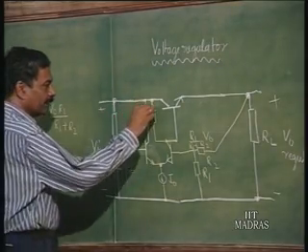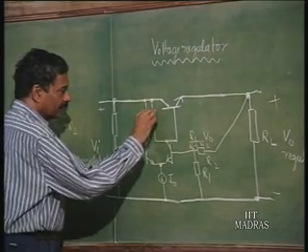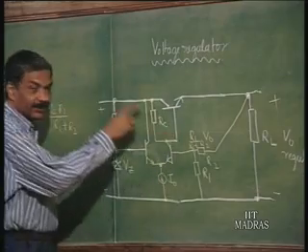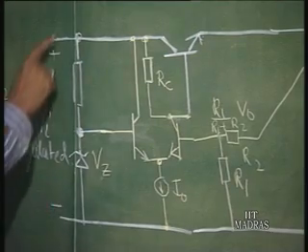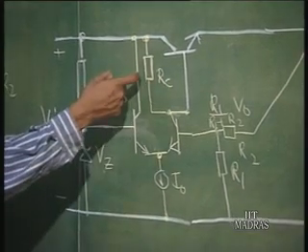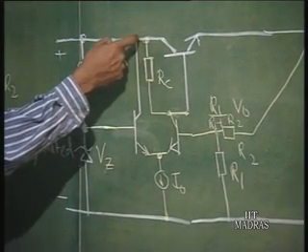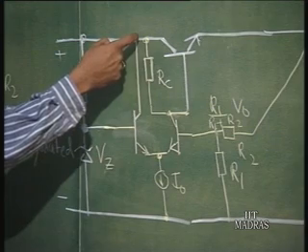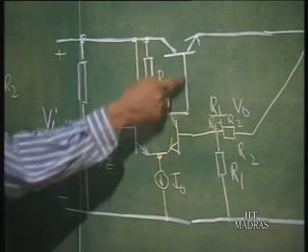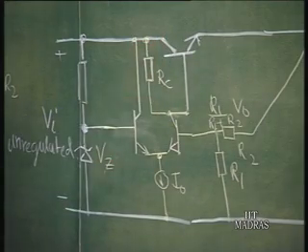So, essentially you can see that this particular structure is a very crude operational amplifier using a single supply. The input voltage itself is biasing this operational amplifier. So, one end of the op amp is connected to this supply, and the other one is connected to ground. Okay. Output goes to the base of the transistor.